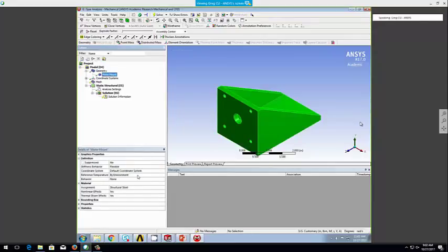I would suggest, and I'll offer this up in the past, when teams had specific problems, the best thing to do would be to contact me and set up a time outside of this, and then I'll give you some fair warnings. A fair warning is this: you don't need to simulate your entire plane, okay? So if you're interested in the strength or deflection of the spars in the wings, you don't necessarily need to model everything. You don't need to model all of the foam and all of the fiberglass. You would model the spar.